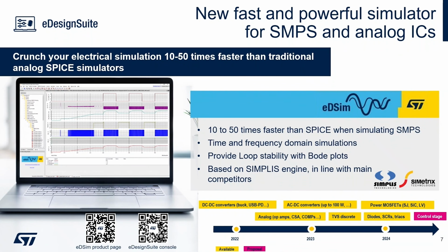This is based on SIMPLIS, which is created by Simplis Technologies, and this tool is 10 to 50 times faster than SPICE simulations for switching mode power supplies. I don't know if you've tried at some point, maybe during school, to simulate a buck regulator using PSPICE. It's painfully slow, and sometimes the simulation does not converge.